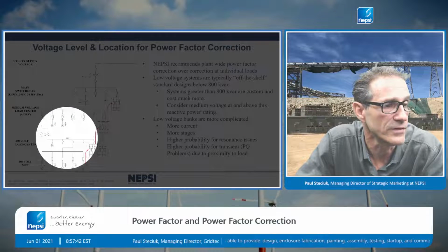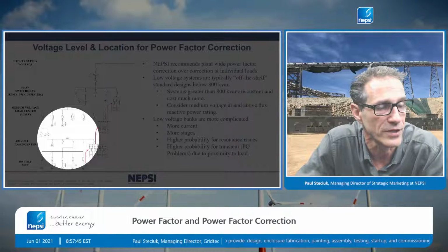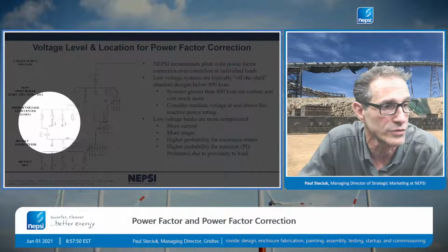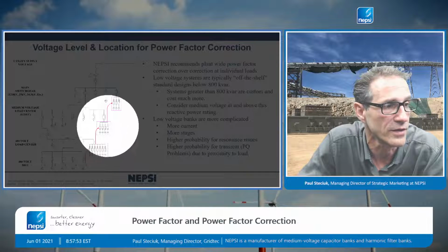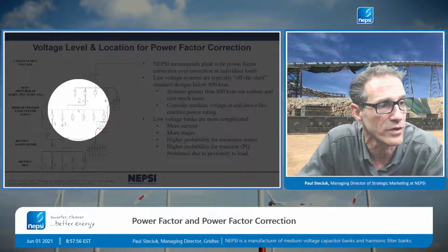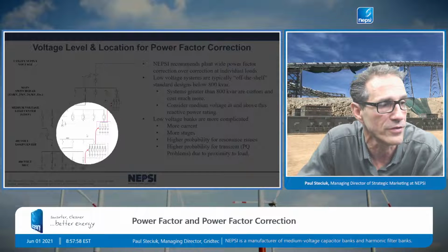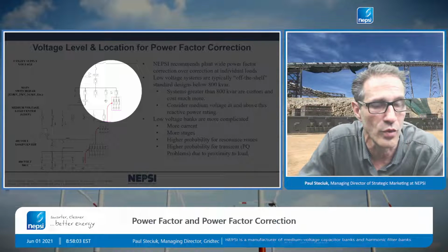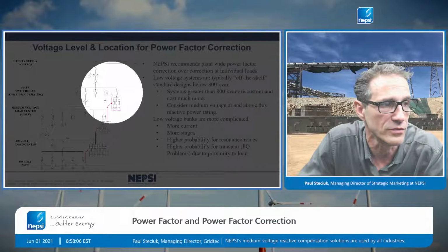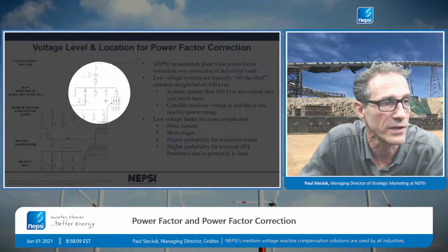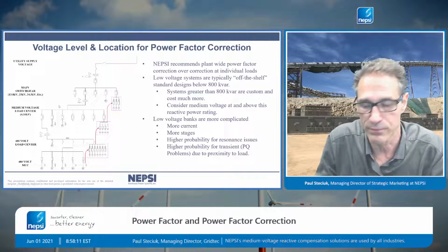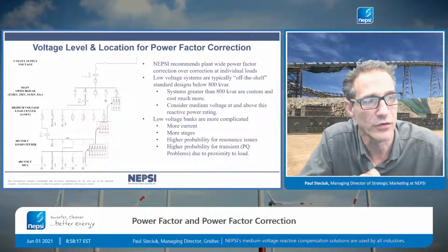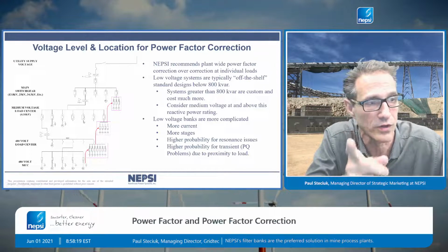You also have the possibility of doing reactive compensation at the 480 volt level, at a medium voltage load center, at large medium voltage motors, or as an open air or metal closed system right here on the main bus bars, and you can step up through the system. We generally recommend that you do reactive compensation at one of these locations, not all of them, because the more capacitor banks you put in the system, the more complex the impedance profile becomes from a harmonic analysis standpoint. Whenever installing capacitor banks, remember, harmonic resonance is a concern.